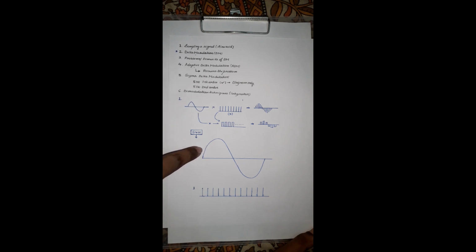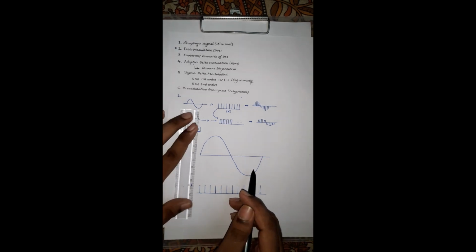So when the impulse train is multiplied with this signal, the discretized sinusoidal signal that will be generated will have the same magnitude that it had in its previous form. That means no amplification will be done over here, because each of the magnitudes at the sampling instances is being multiplied with 1. That's why the magnitudes of the discrete sinusoidal signal will remain the same. So let us see what is happening over here.